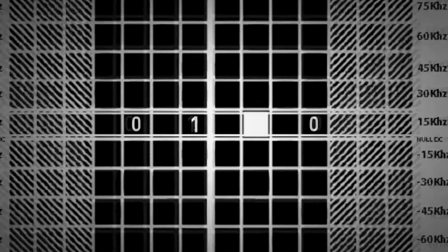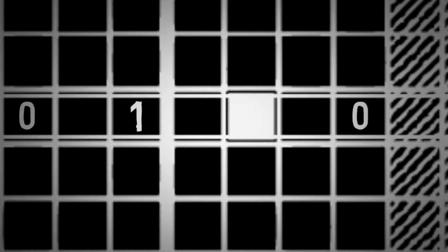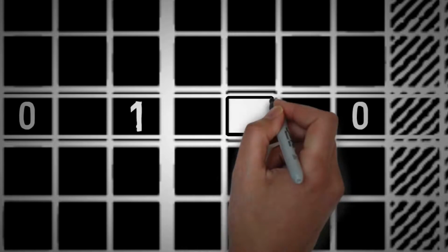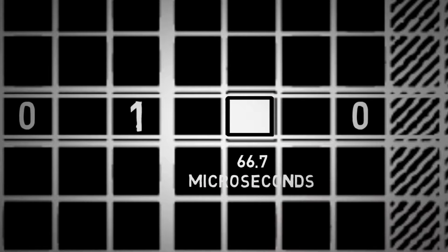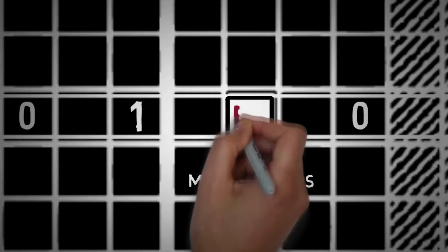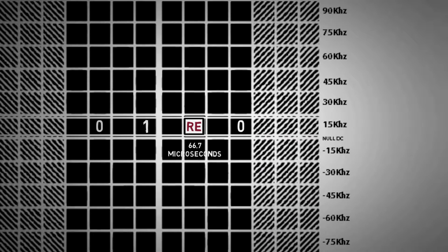As discussed earlier, data is transmitted in OFDMA over parallel subcarriers of 15 kHz. The subcarriers are further divided on the time axis as blocks of one symbol duration, or 66.7 microseconds. This basic unit is known as a resource element. Each resource element carries one symbol.